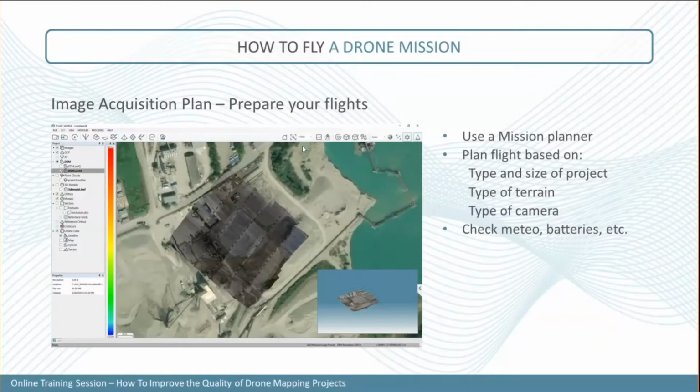This way, when you do the tie point extraction, it should be a bit easier to tie all those images together. I know it's kind of not intuitive because more images may take longer to process, but in the end, it's going to save you some time on the editing in the aerial triangulation module.